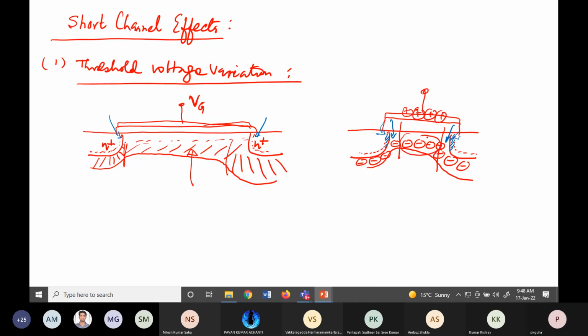You have to, because this is a capacitor effectively, right? So you see the gate will now see that you need to image fewer charges, so that will reduce the effective threshold voltage, okay, or the threshold voltage is going to vary.